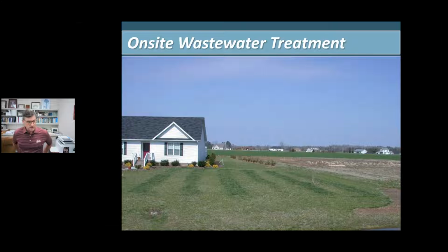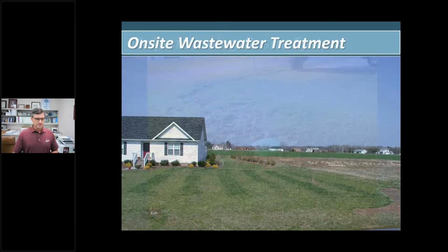Because in this scenario here, your leach field is not necessarily draining that well. There may be some clogging in the field lines itself due to one thing or the other, fats, oils, greases, or solids being pushed down into the lines. But nonetheless, you're seeing that moisture rise as a result. You're seeing these lateral lines, which when we think about the dry season, this is one of those benefits you can have with the dry season.